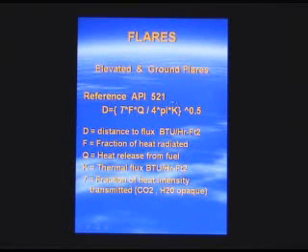Flares, they're very critical. They are basically a system safety device, a process safety device in case you have to de-inventory a plant quickly. This is the most common accepted means to do that. The reference for the design is API 521. This is probably the principal equation in API 521 for flare radiation.